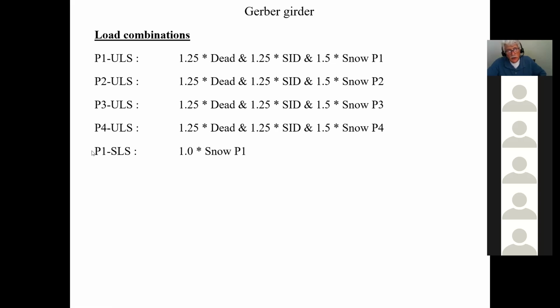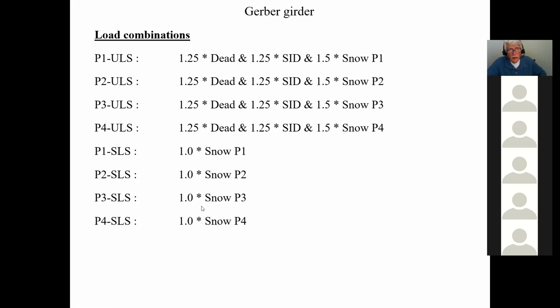So therefore, we're going to check serviceability under load number 1, serviceability under load number 2, and serviceability under load number 3. So we're going to have 8 load combinations, okay? 4 for strength, 4 for service, and we'll check each one to see what the results are.